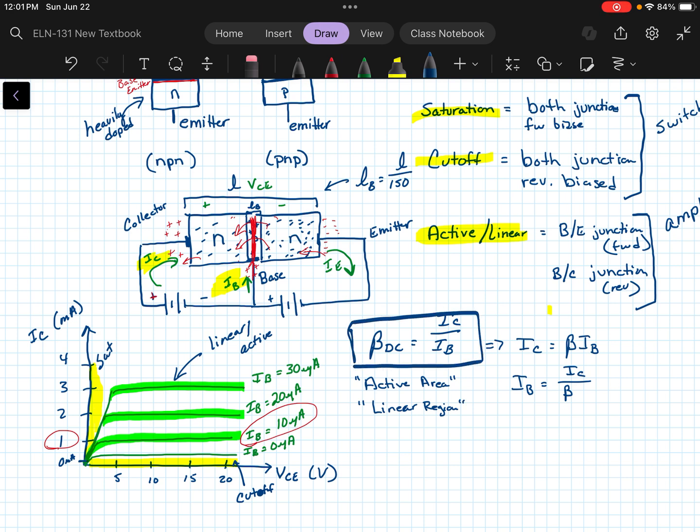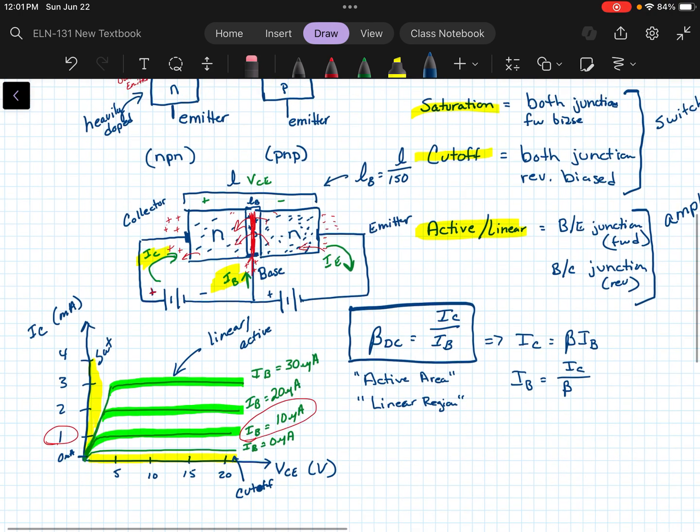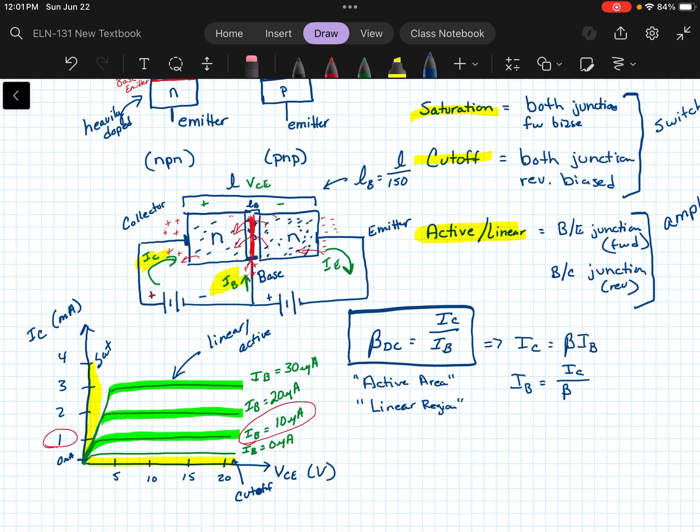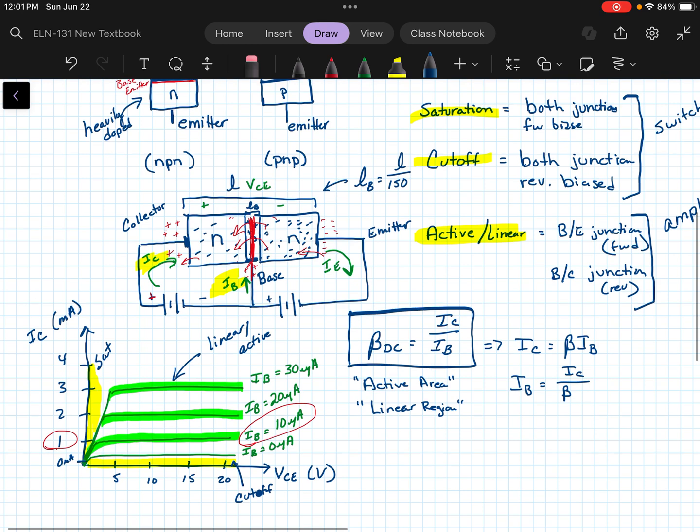If we enter the saturation, of course, it's not going to be true anymore. That's where we have that unbounded current. Well, we'll have a maximum saturation current. We'll talk about that in a minute, dependent upon the circuit. But it's pretty much the maximum current we would expect to see, and we wouldn't get any more current and no voltage drop across the collector and the base. Okay, so what does all this mean in terms of our circuit?